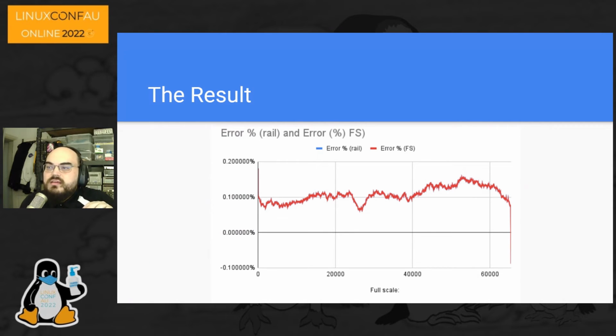So I can see that the real bottom of the range and the real top of the range, it's not so great. But actually, we're hovering around 0.1% absolute error, and relative, that's 0.04-ish% plus or minus, which, okay. I don't quite like that dip just before half scale, and it unfortunately turns out that half scale is extremely important, so I might do some design changes there, but I've got the information to do those design changes now.